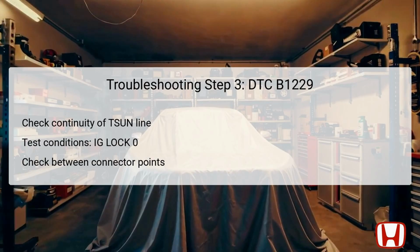Next, you will check the continuity of the T-sun line, which is critical for the sunlight sensor's operation. Begin by turning the ignition switch to the lock position to ensure safety. Disconnect the climate control unit's 32P connector along with the sunlight sensor's 5P connector.